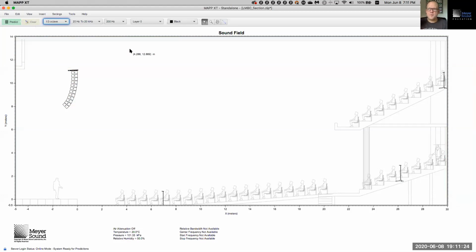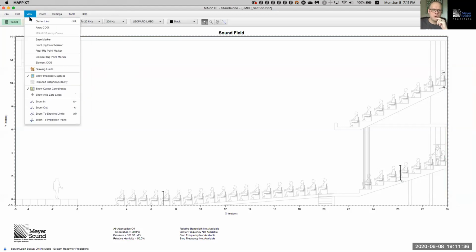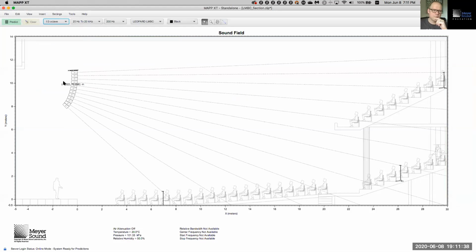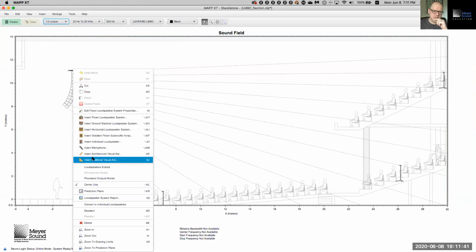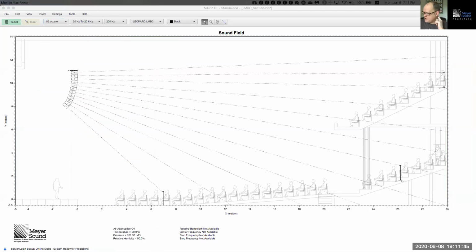If there are no competing loudspeakers in the same area, then EQ, then gain shading is a viable solution. But if there's no isolation, if there's no separation, then you will not be able to make the most out of EQ. So in order to make you appreciate that, let's go to our properties and let me show you only the top and the bottom loudspeaker.